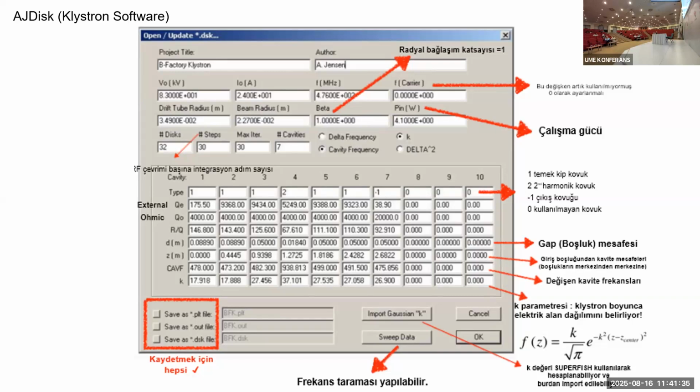You remember the magnetic coupling, loop coupling. If it's undercoupled or overcoupled, you have to turn a little bit right or left and follow it from the oscilloscope or instrument which you are using. It deviates because the surface of the loop is not exact. It can't be done exact.